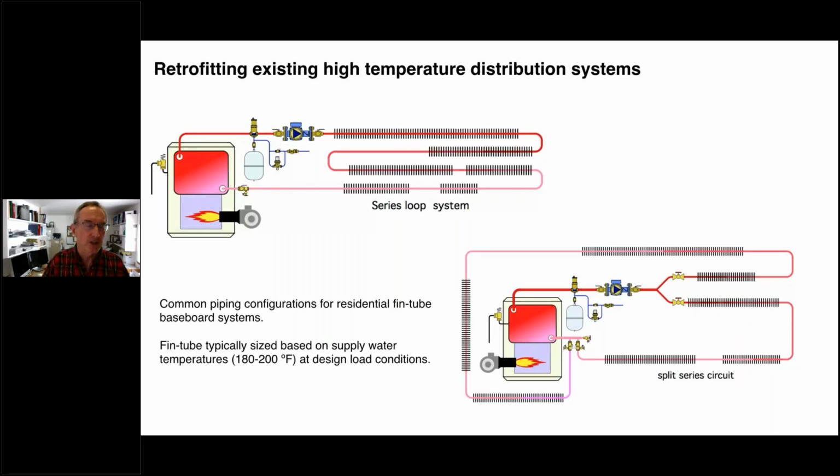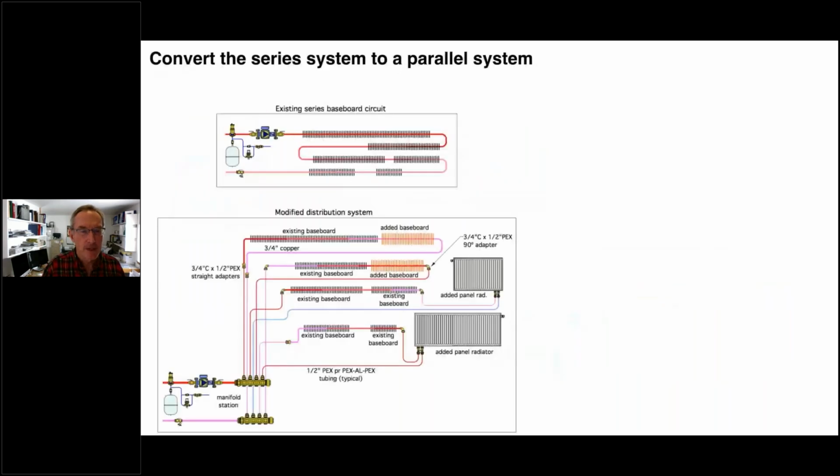There are dampers that you can close that will reduce the output somewhat, but if it's undersized, there's really nothing you can do that would allow you to bring that one room output up without overheating the other rooms. So series piping loops are very much legacy in terms of modern hydronic design.